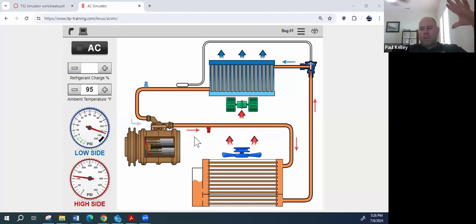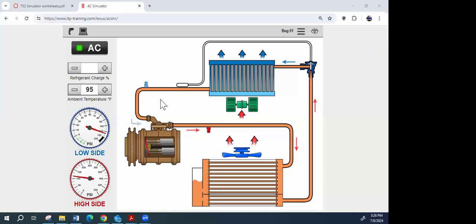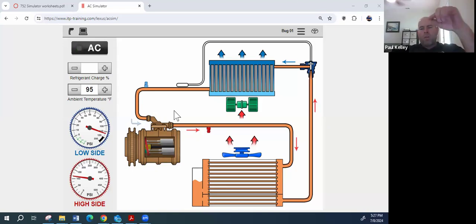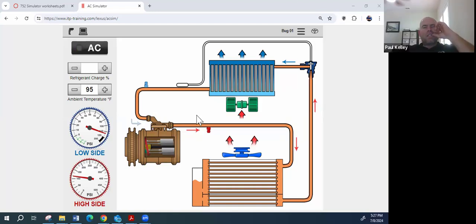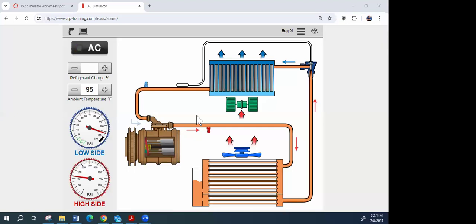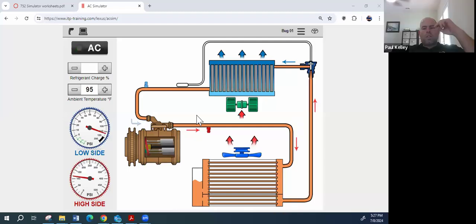Let's just pick one that we can eliminate. Anybody pick one. I want a few people to pick one. Power? Okay. And I agree. Luis, how would you verify that? Either the fuse or the relay? Yeah, but how would you verify it? You tell me components, tell me your test, tell me what you do. You could just check if it's getting voltage at the fuse or just swap out the relay. True, you could do a relay swap. You could check voltage at the fuses.